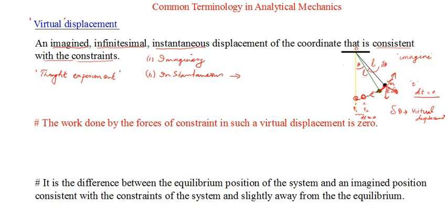Or I can say the virtual displacements are usually written as delta r. And remember, real displacements are represented by dr usually. If r is the position vector, then dr represents the displacement vector, right? Which are real displacements, which happen with the passage of time, with a time interval of dt between the two positions. So usually we say that this delta r, or the virtual displacement delta r, is regarded as the displacement dr which happens with the condition that dt equal to 0.